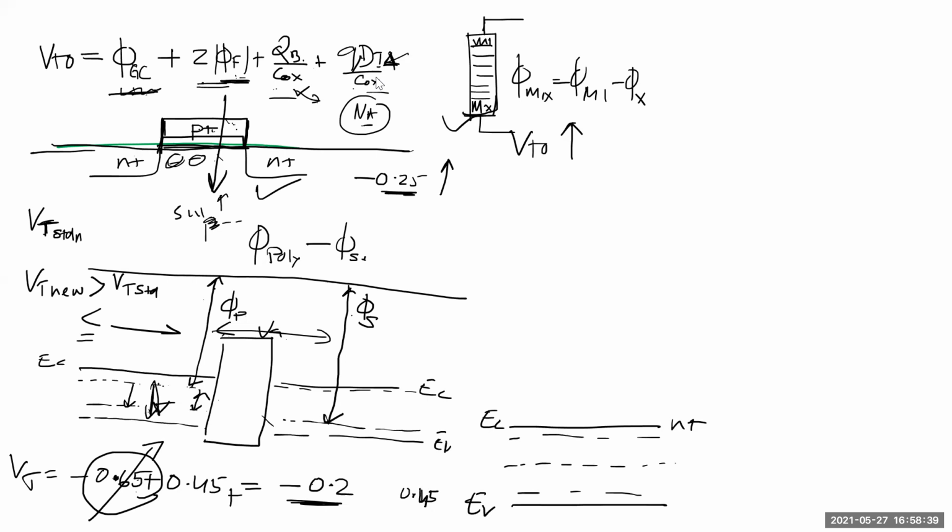In fact, ideally that's what you would want for NMOS. Then you'll get an enhancement device by default. You don't have to do any adjustment. But as a process, if you do that, then you can't do self-alignment. And if you don't do self-alignment, then it's extremely difficult to do fine line transistors.